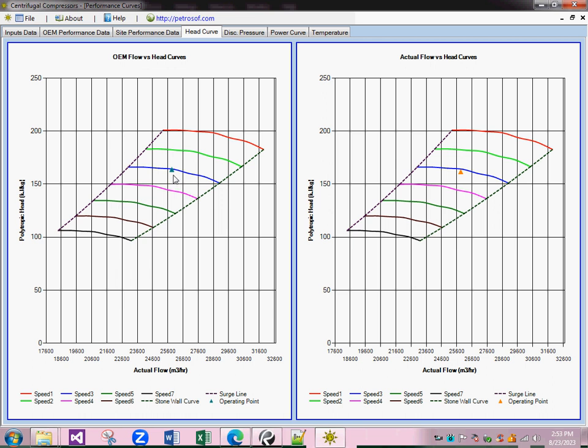Also, to show the compressor running under the surge flow condition, I will change the value again. Here in the operating condition results, you can see down below, the compressor condition is represented with the description saying that the operating point at the side base condition is under surge.